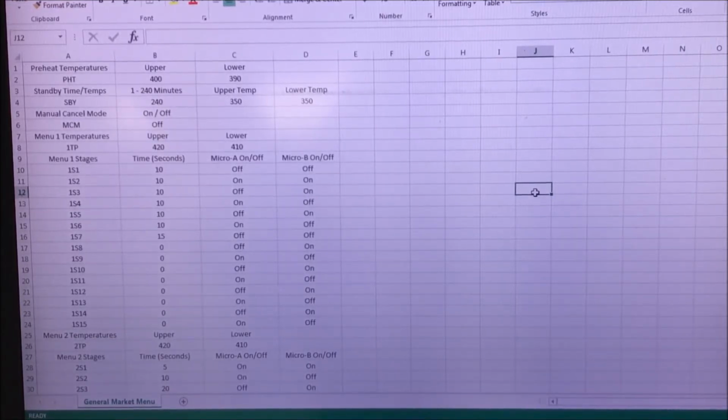Note, some units only have 4 menus. An 8-button program will not upload to a 4-button unit. When you have changed all the menus to your liking, you will then need to save the program, making sure the file is saved inside the 1150 app folder. Failure to do so will result in an error code when uploading the program.